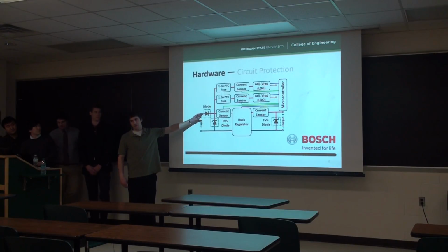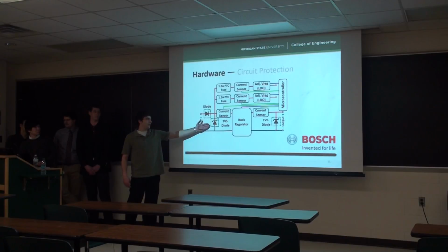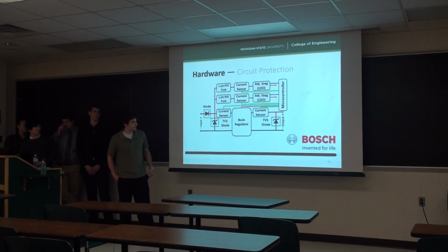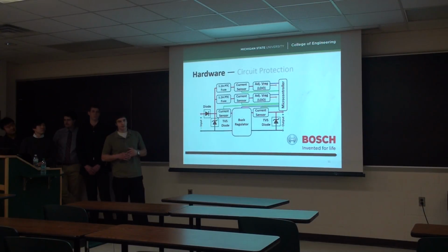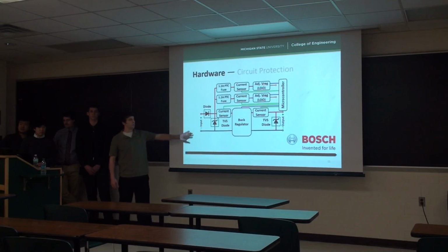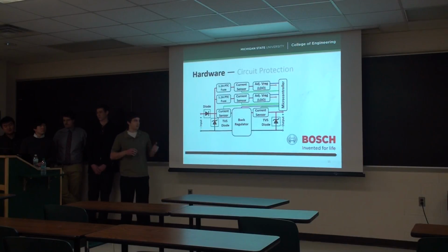We chose to use a single diode instead of another MOSFET for reverse battery protection. The TVS diodes help with transients, and also over voltage protection. And the one on the output has to be sized outside the limits that the output will actually see, because the whole purpose of this project is to actually create the transient responses and transient voltage conditions which cause problems.